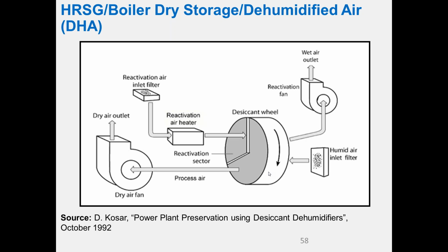When you come up to temperature and pressure, there's stresses applied to the plant. You can get these things called stress corrosion cracking, and corrosion fatigue, particularly in turbines and superheaters and heat exchangers that have got some kind of tensile stress present on them. So something you need to watch out for.